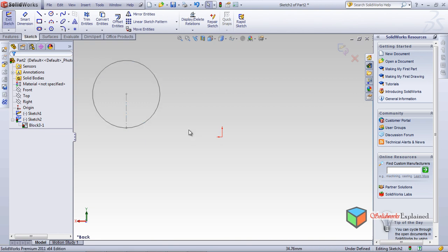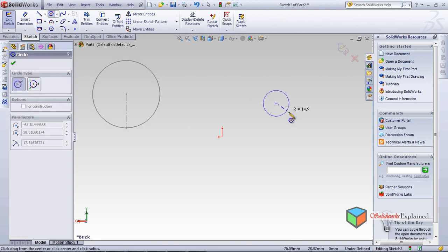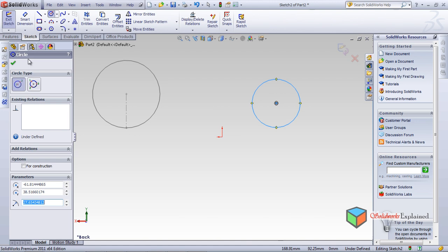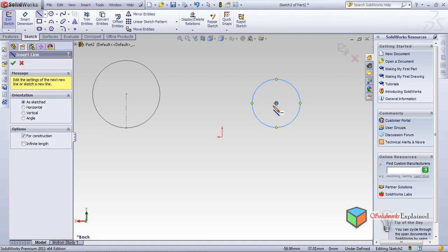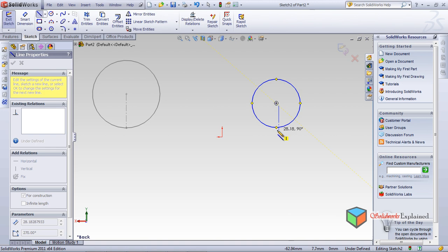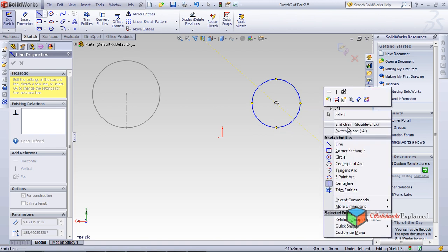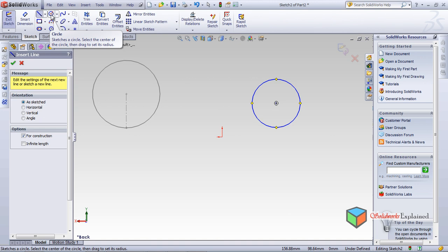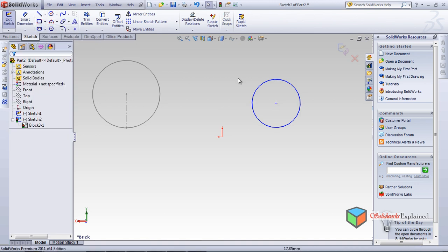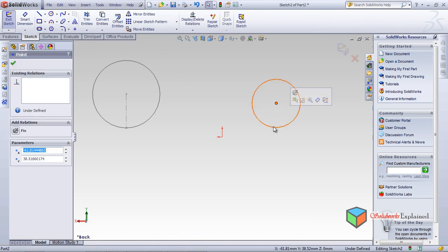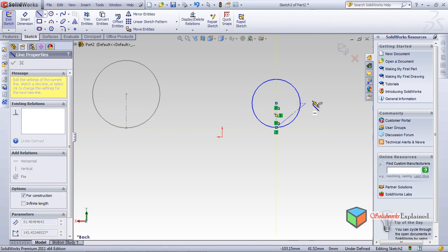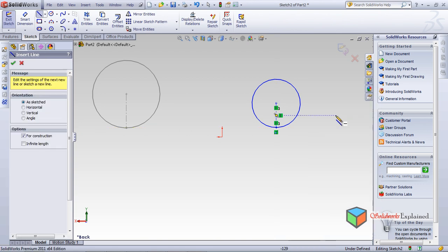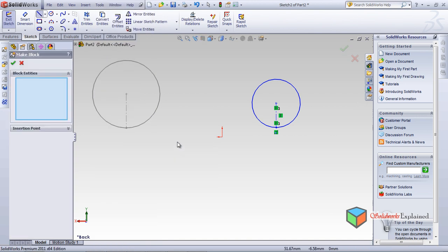Okay, this is done. Now again I will select a little bit smaller wheel, and then I'll make a center line as usual. From here, this is a wrong center line, and chain. Again select a center line properly. Not able to select properly. From here to here, right click and chain, and again tools, blocks, make. Okay, so this is done.